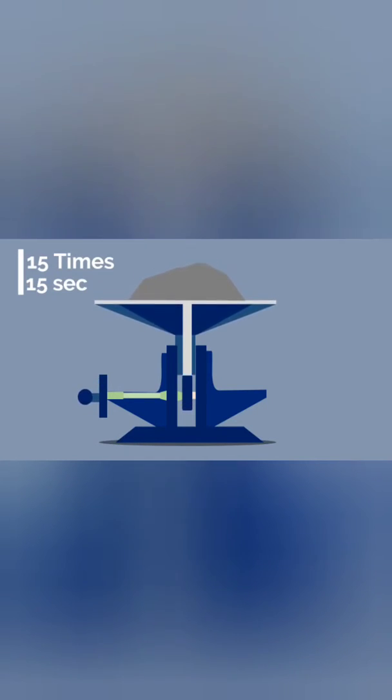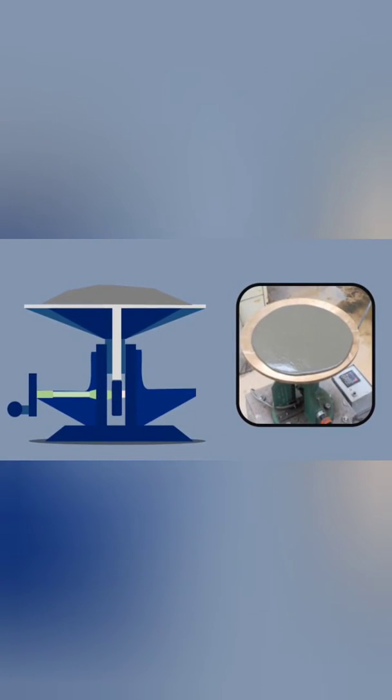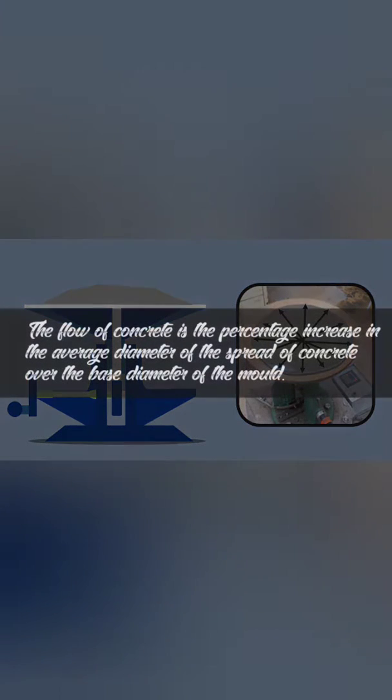The table is then raised and dropped 12.5 millimeters 15 times in about 15 seconds. The diameter of the concrete spread is measured in about 6 directions to the nearest 5 millimeters and the average spread is noted. The flow of concrete is the percentage increase in the average diameter of the spread of concrete over the base diameter of the mold. Flow in percent is calculated as (spread diameter in centimeters minus 25) divided by 25, multiplied by 100.